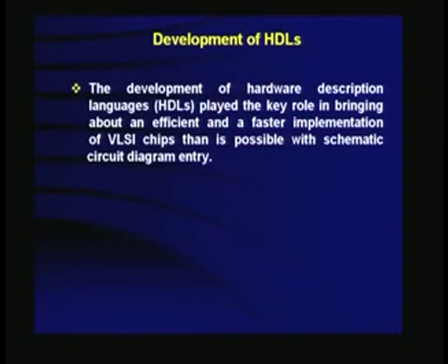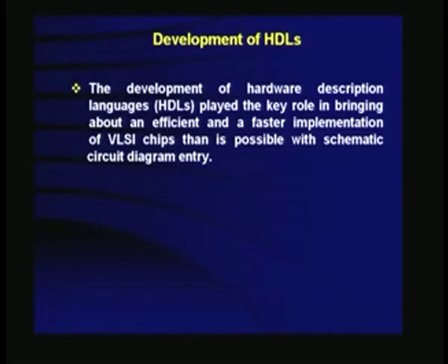That means you need a computer language in which you can describe your design. Such a description is called hardware description language. HDL stands for hardware description language. So we have to develop a hardware description language. This was the key thing. Your design on paper is brought into a program which can be compiled and mapped onto a device which is available to you. This bridge is the hardware description language. It is a very key component that made the design efficient and fast, playing a key role in bringing about an efficient and fast implementation of VLSI chips, which is not possible with schematic circuitry.